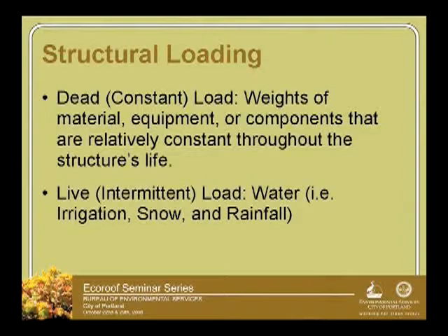that membrane. And then there's also live loads or intermittent loads that need to be considered, and those are water, irrigation, snow, rainfall, people, if you're up there maintaining the equipment or looking at the Ecoroof, those kinds of things. So those are just two terms we talk about, and really the Ecoroof things that we talk about fall into that dead load category.